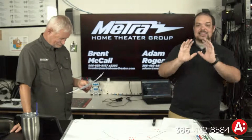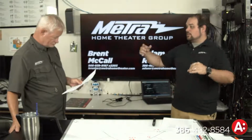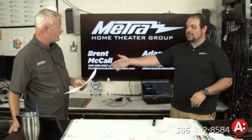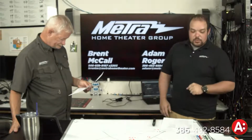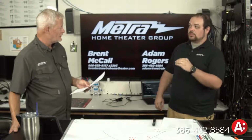So at this level, 51 watts at the powered device is a lot of power. If you convert that back to, say, 12 volts and do the math, you've got quite a bit of amperage to work with at the end of that line. And it's the amperage that runs stuff. Exactly. So that's 51 watts, with 60 watts at the output, and then Type 4 is 71.3 watts, with a full 100 watts maximum output at the PSE.